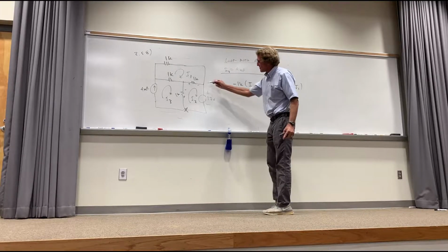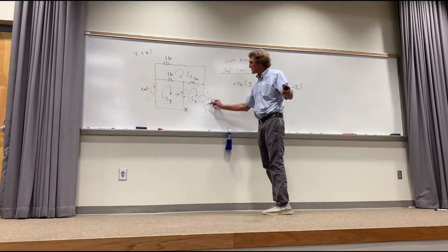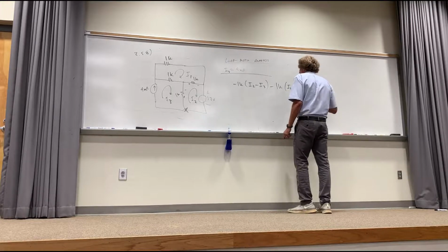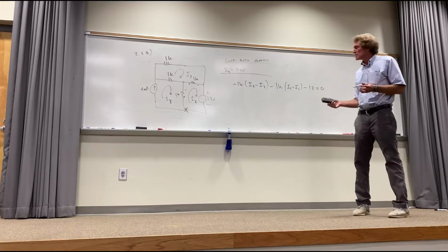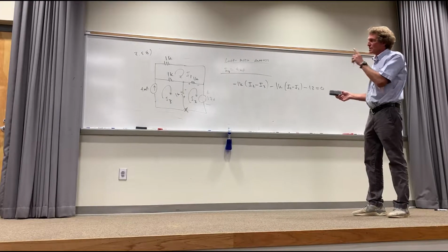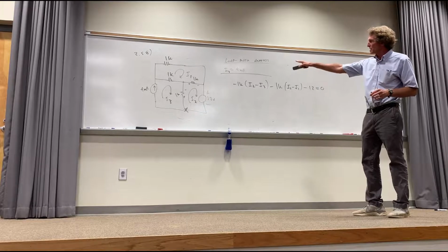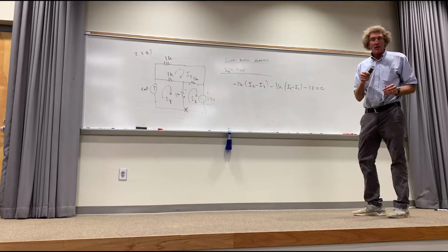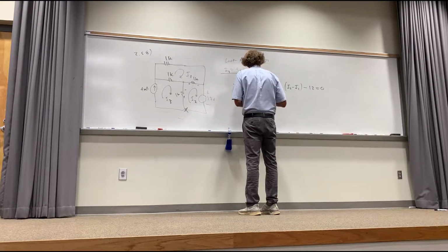And finally, I go from here to here, there's a voltage. Did I increase my voltage here or decrease it? Drop it, minus 12, right? So it's minus 12 equals 0. Now, before I continue, I know I'm going to knock off the negative signs, just listen to this. I'm going to replace I3 with the actual value of 4 milliamps, okay? Everybody see that?